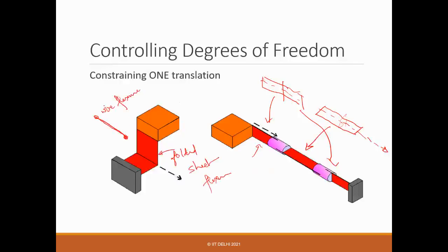So here you have larger area available to you. So many times the clamping is easier. The assembly is simpler compared to this wire flexure. That's why many times it's preferred. At the same time, it has a wider area, and then the load capacity, the buckling load, everything will be improved.